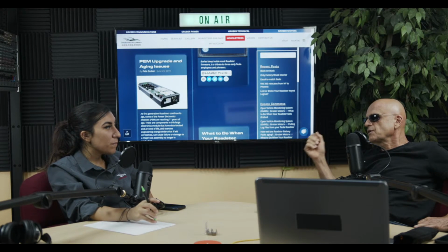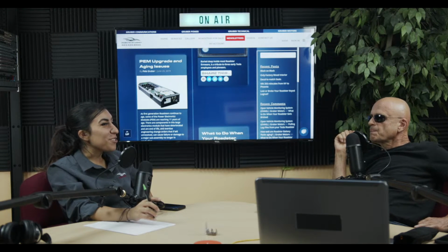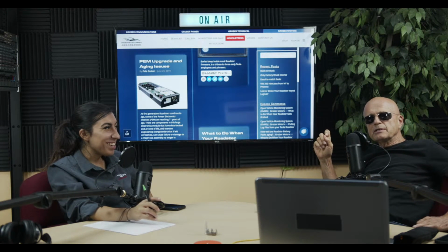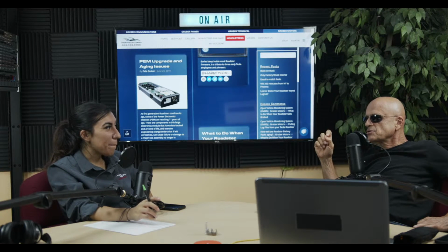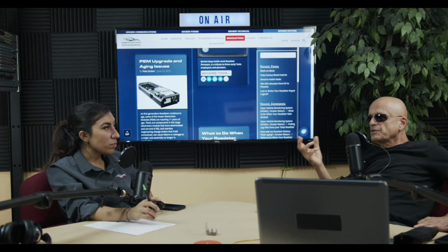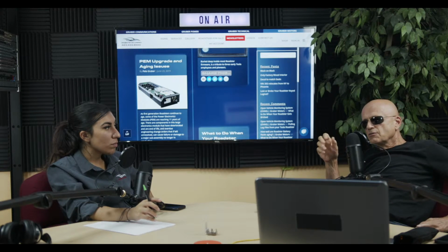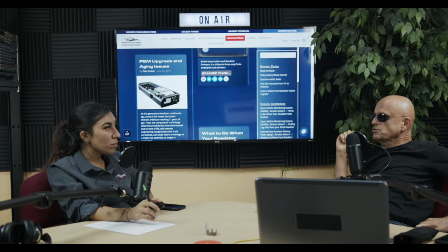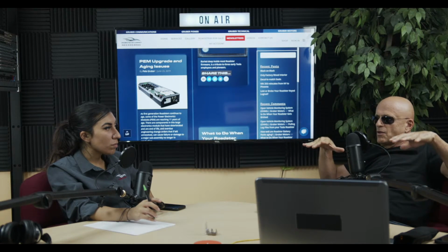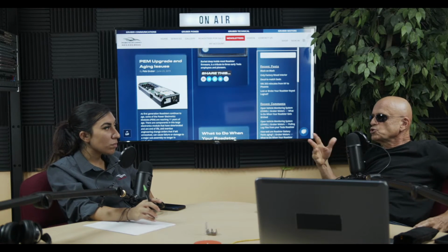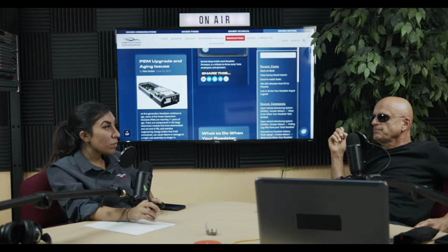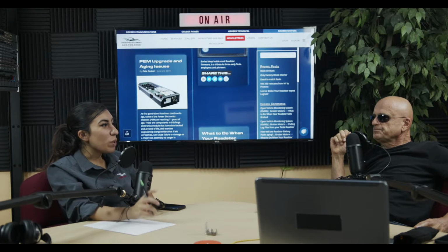If you blow a fuse, that's fine. You can change that easily. Okay. Can this car actually blow up? Well, good question. The one in Europe, there was a capacitor that became resistive to the point where it began to overheat, and it built up pressure, and it actually blew up. The problem with that is a capacitor has metal foil inside it, tightly wound, and when it blows up, you get all of these metal fragments, which are conductive, flying around the inside of your power electronic module with lots of circuit boards, and all that conductive material, as it lands on the boards, can short things and cause even more damage.